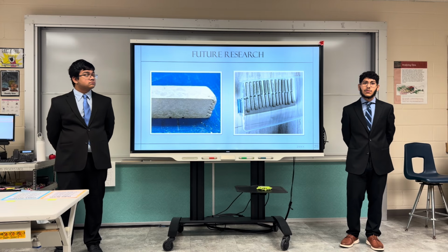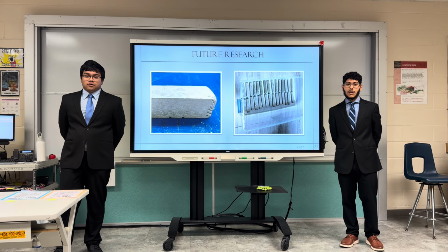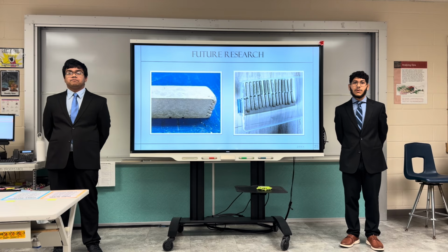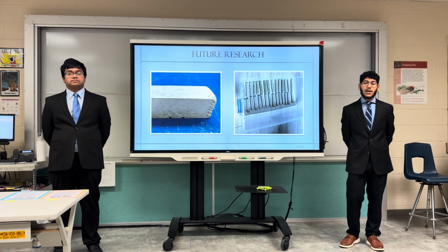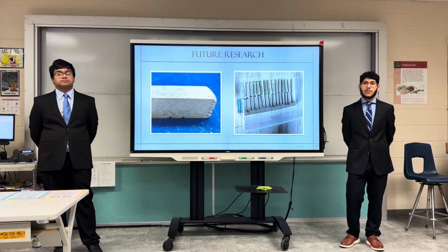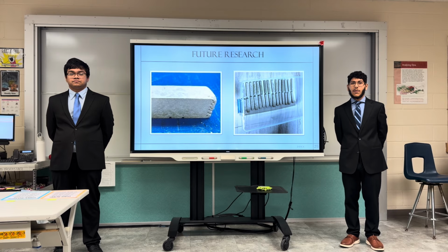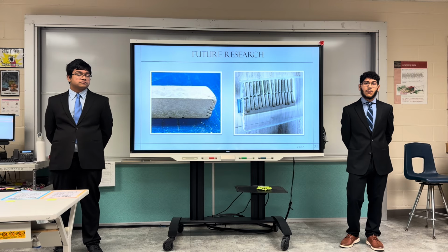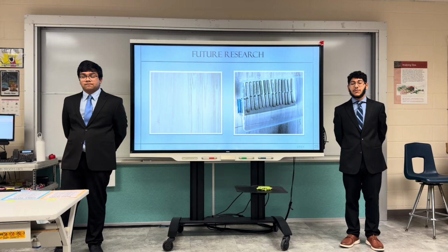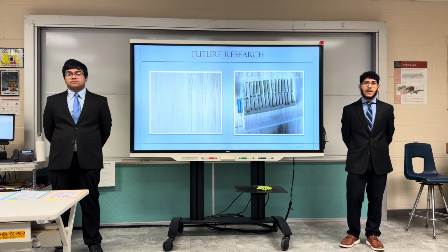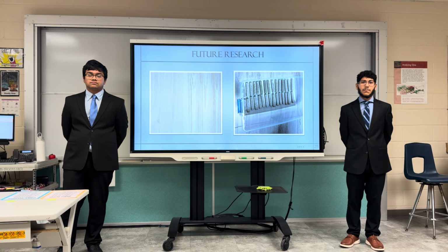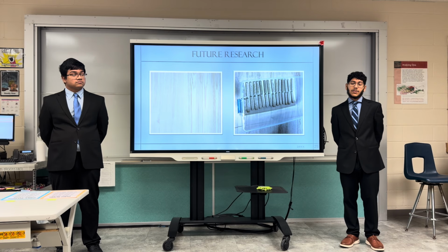Additionally, another problem we encountered was with the treatments, as we had put the uncured concrete beams in a tub and then put a lid on top, but when we had closed this lid, water ended up building up and condensation caused the water to pool at the bottom, leading these uncured concrete beams to become somewhat cured in some areas as they were somewhat covered by water. So in the future, to fix these problems for the molds, we'd maybe try a different design, or maybe making them out of wood so they can be pulled apart and disassembled and maybe reused, which would hurt the concrete less. As well as for the treatments, maybe removing the lids, so making sure water doesn't build up and fill with water and actually cure them.